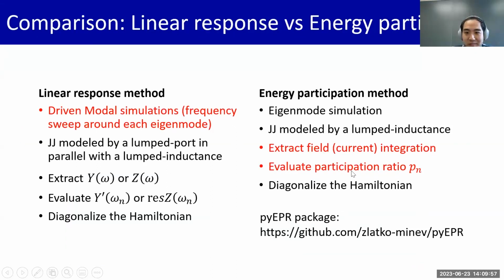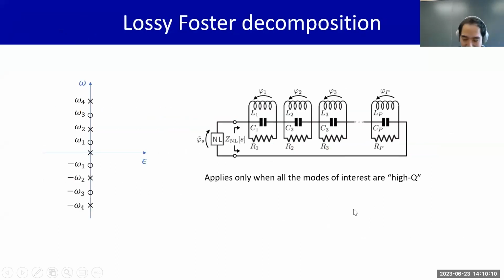And up to now, I've only talked about linear lossless circuits, but in an actual experiment where you want to include loss as well, what we usually do is the so-called lossy Foster decomposition, which is actually not an exactly correct thing to do, because the Foster theorem does not apply when you have a lossy response function.